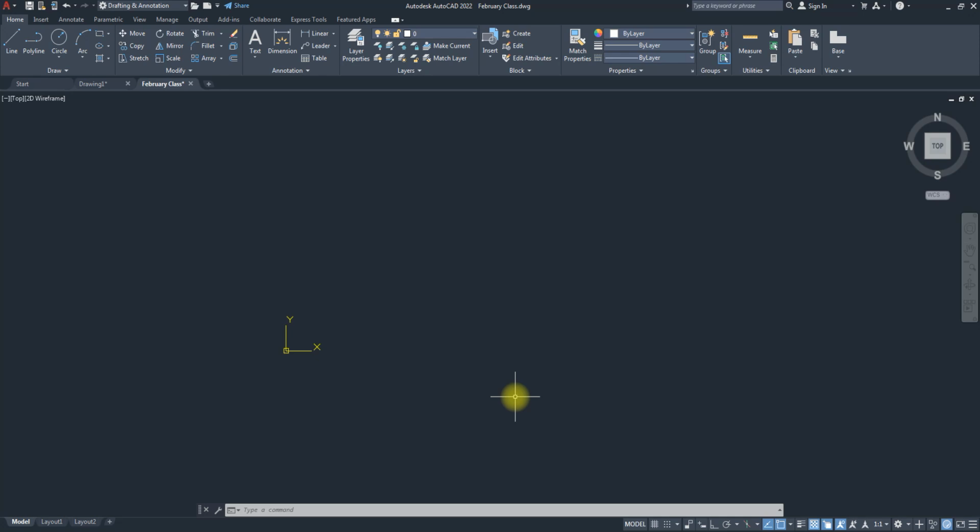Remember, all those grid lines have values, they are marked. So you can actually utilize those values to create your shape. What will aid you in creating using those grid lines is the snap. The snap is more of a magnetizing effect to those grid lines.